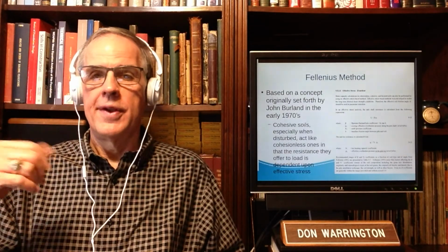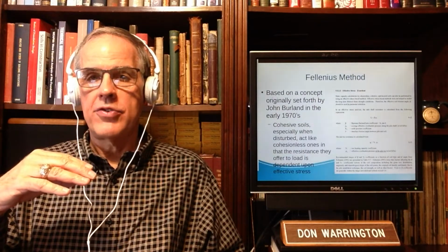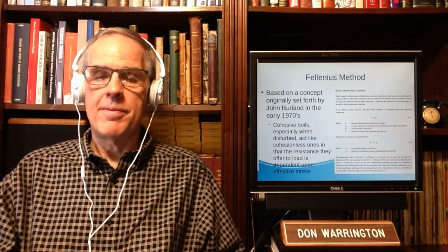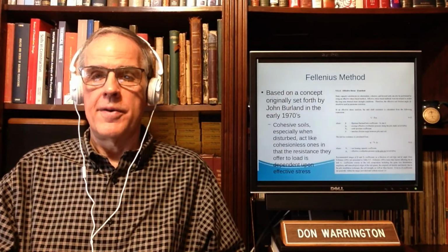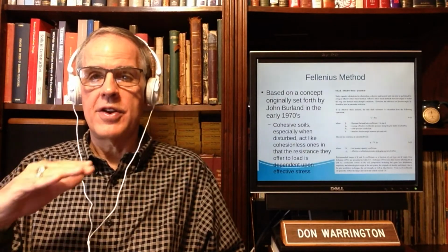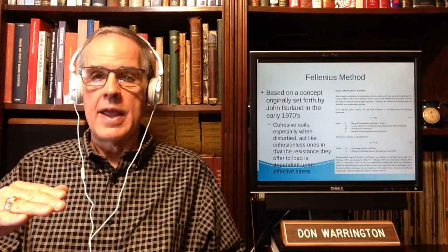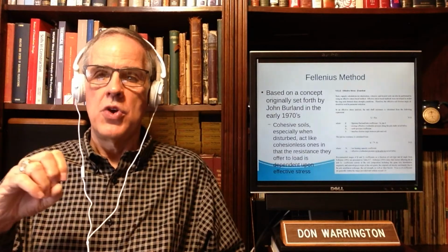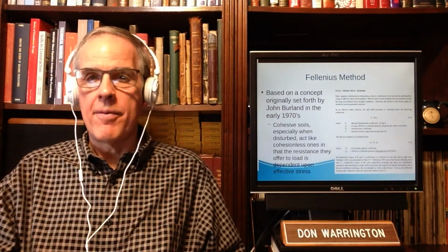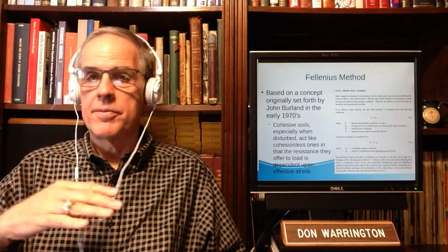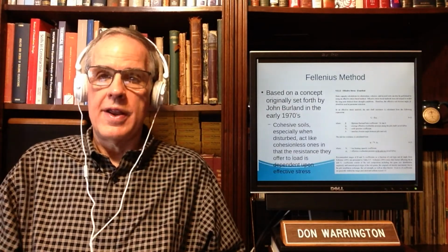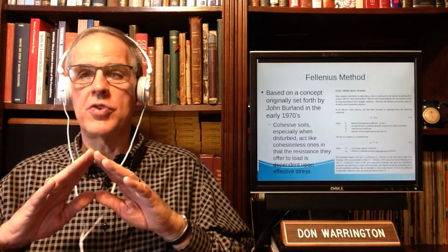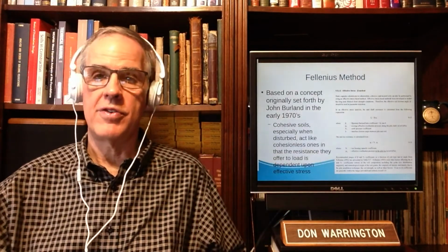With cohesive soils, there is a relationship between Cu and effective stress, which basically means that we still need to know the effective stress even in cohesive layers. Depending on how we do the math, and I've got some material on my website which discusses this issue, we can set them up as either alpha methods or beta methods. It seems to me a lot easier to set the whole thing up as a beta method. In other words, if you compute the effective stress, why not just use a beta method?